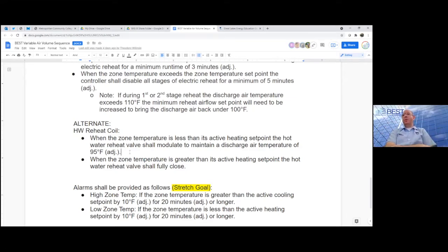But if you're working with smaller diameter or smaller VAV boxes and less velocity coming out of them as a result, sometimes that really hot, effective heating air doesn't make it down to the spaces where it's going to effectively heat your space. It's going to kind of hang out up at the top of your zone, right along the ceiling line, and just get sucked back into the return. This does a couple of things.